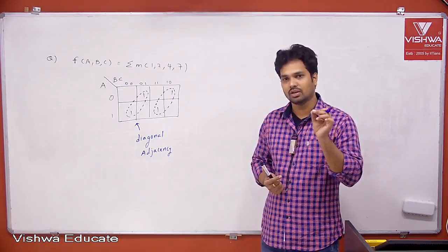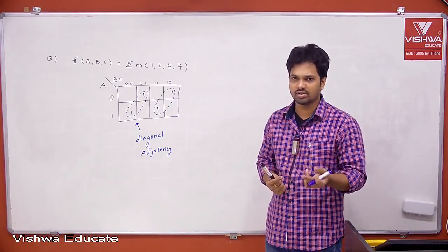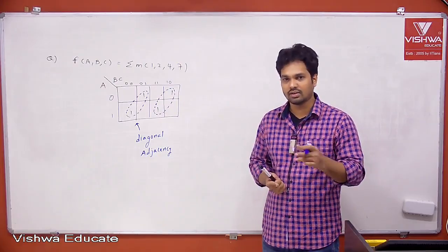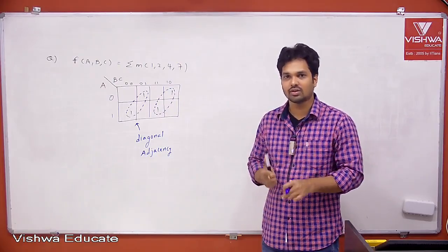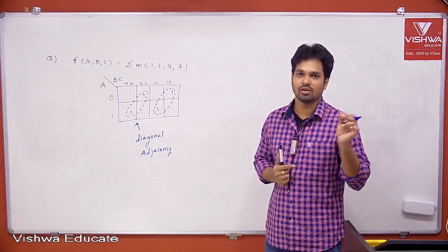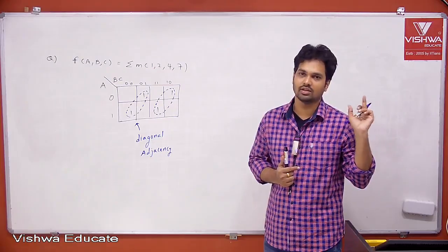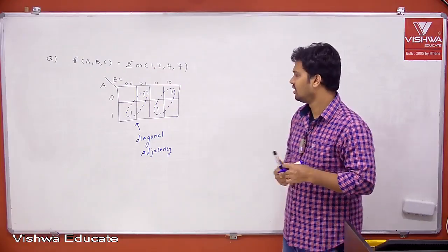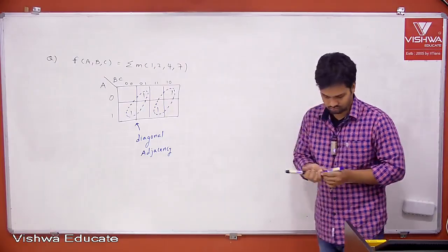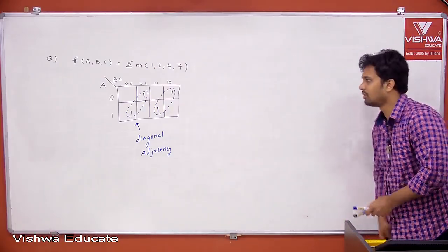If each minterm contains an odd number of ones, as you know earlier, XOR. Even number of ones, XNOR. If both of these conditions are not possible, you can check, the answer will possibly be an XOR, XNOR combination. We can see that. Okay. First, copy this. I'll give that statement. Copy it.